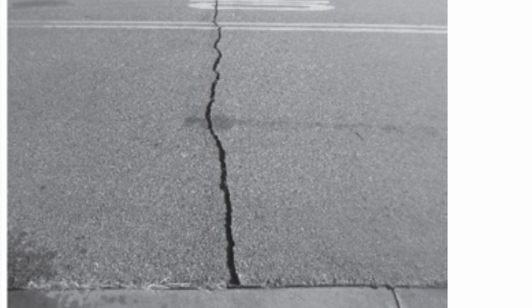A transverse crack, also called a thermal crack as it is not load-related, runs perpendicular to the pavement's centerline or lay-down direction, as shown in the figure. This is caused by single-day extreme cooling of the pavement or cyclic cooling-heating loading. It allows moisture infiltration and causes increased roughness. Causes: transverse cracking occurs due to shrinkage of the HMA surface as a result of low temperatures or asphalt binder hardening. Proper selection of asphalt binder considering the possible single-day extreme low temperature may avoid transverse cracking. Treatments: based on the crack depth penetrated, a thin or full-depth replacement may be required.